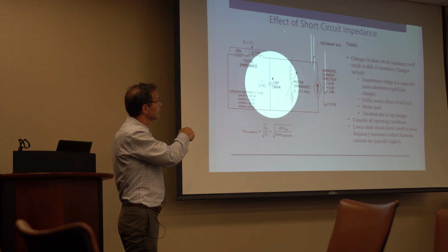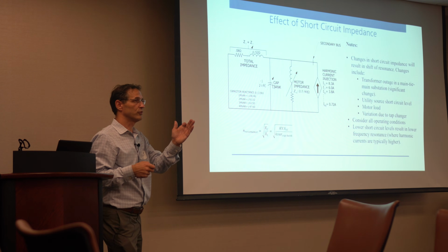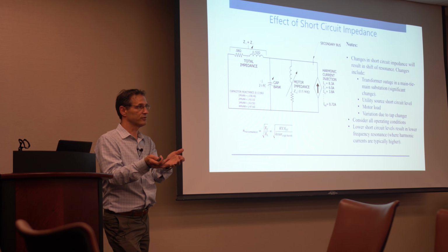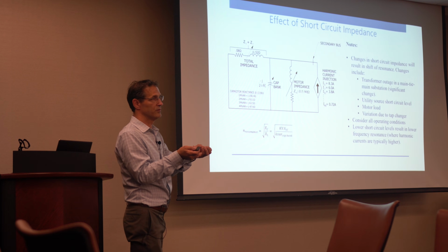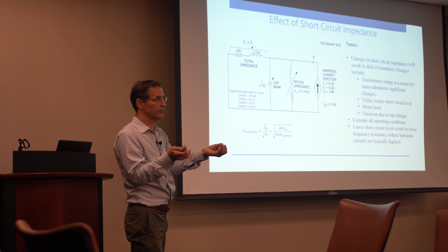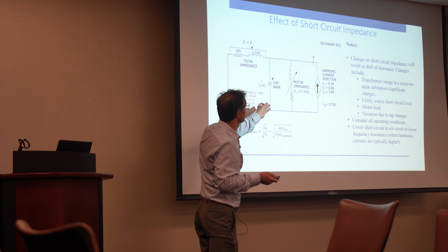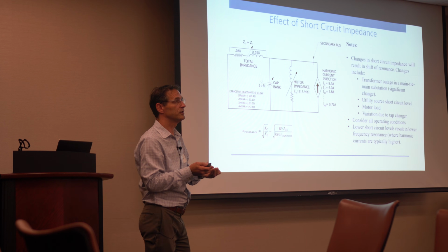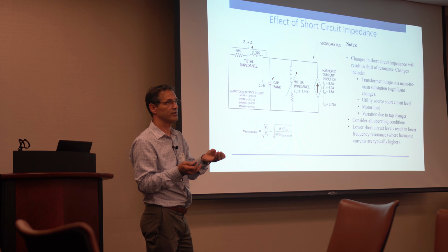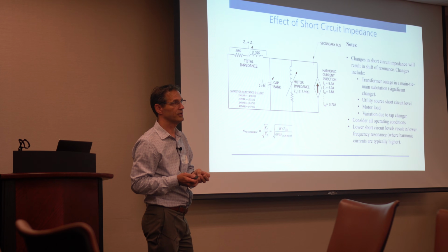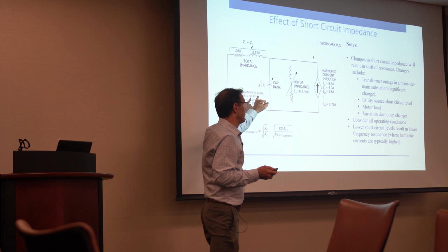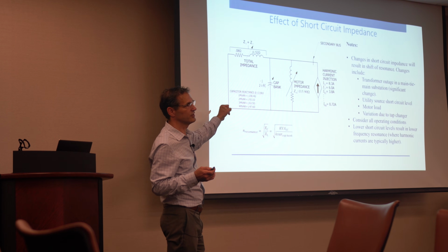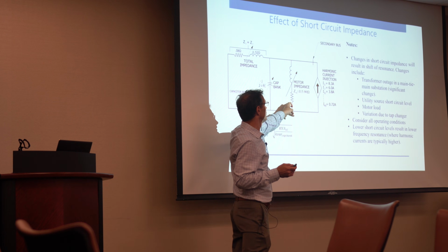The capacitor bank can also come in at 0 plus 10%, right? So do your analysis, and you're going to make an assumption, but the value you get from ABB or Cooper or GE or NEPSI, I guess, will be some value, right? But it's going to be 0 plus 10 because that's what the IEEE standard says, 0 plus 10. They're testing to that. For your information, generally it's about 0 plus 2. They're pretty exact. The manufacturers can hit it pretty good. But the standards say 0 plus 10.